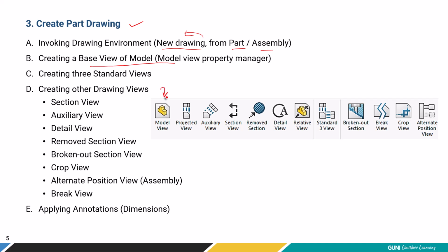For that you have to use the model view property manager. After placing a few views, you can project the required views. Either you can create the three standard views. Now these three standard views are front, side, and top.